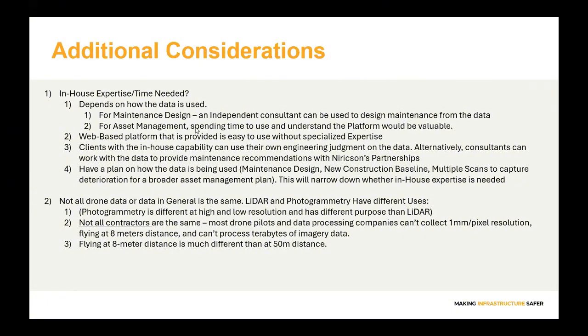And again, I would say not all drone data, or data in general, is the same. LiDAR and photogrammetry are very, very different use cases. I would use photogrammetry more for visual defect mapping, and LiDAR more for geometries, getting accurate geometries of your structure, and maybe, depending on the accuracy, some movement monitoring. Whereas photogrammetry has a higher level of detail, allowing you to see some of those smaller cracks.